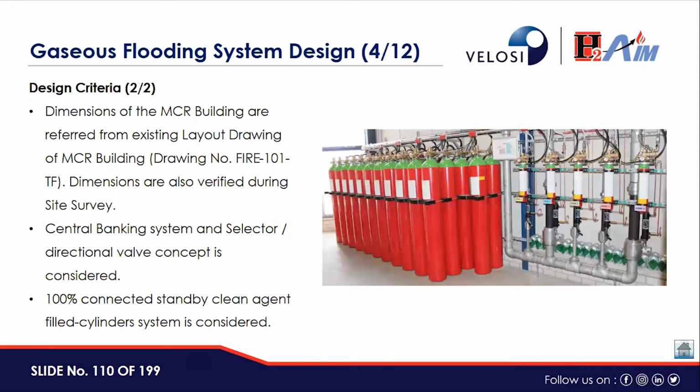Dimensions of the MCR building are taken from existing layout drawings. The dimensions were also verified during the site survey. Central banking system and selector directional valve concept is considered. 100% connected standby clean agent filled cylinders were considered for designing the gaseous flooding system.